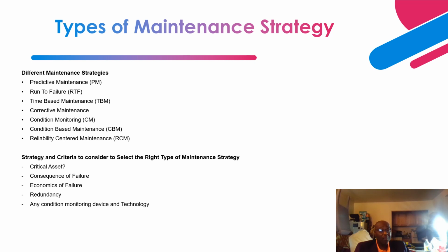On a daily basis, as a maintenance engineer in charge of substation assets, if you receive a component that is defective, you have to put in the required maintenance request and material requisition to replace that component of that equipment. That is called corrective maintenance. So corrective maintenance comes in anytime, on a daily basis, or maybe during a time-based maintenance.